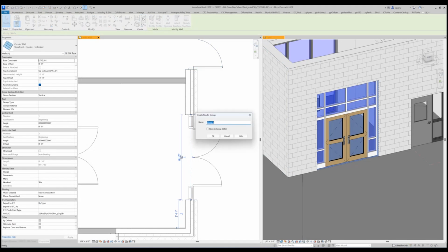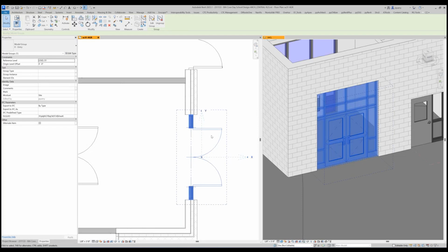Now, chances are this is going to be aluminum frame type or door frame type. I don't know how many you have. So I can usually put it as an X dash, and then I just give it a description. So that's the name of the group. First thing I do is move this origin point, and this is crucial. If you pay due diligence to this, you can switch these out with other ones and you won't have to adjust anything.